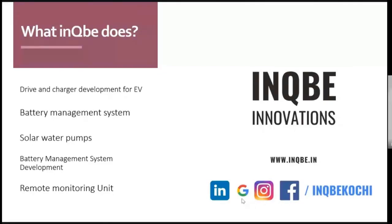Sir, you said that floating point is there, which is used for MPPT controllers also in microcontroller applications. Floating point you have taken in STM32 and C2000. MPPT is a very slow application, because when we apply a change or perturbation, such as in P&O or incremental conductance, we should wait for the response. That means there is a lot of time to compute.